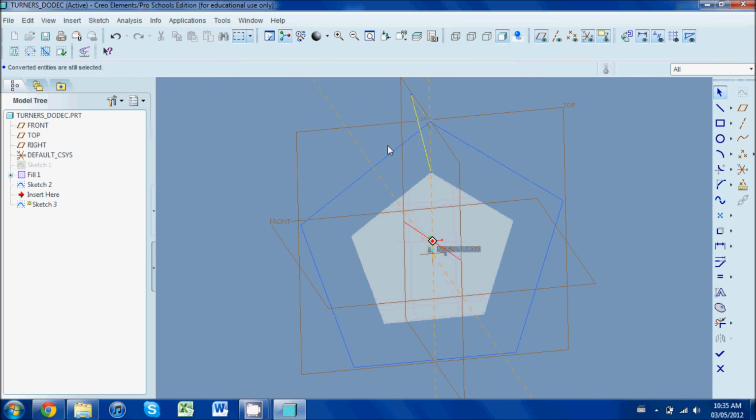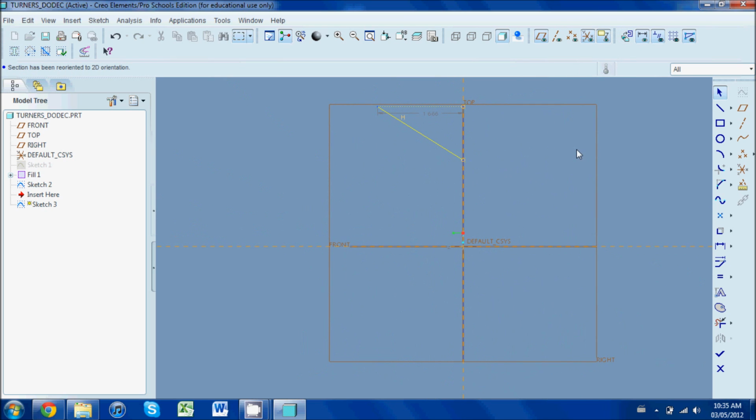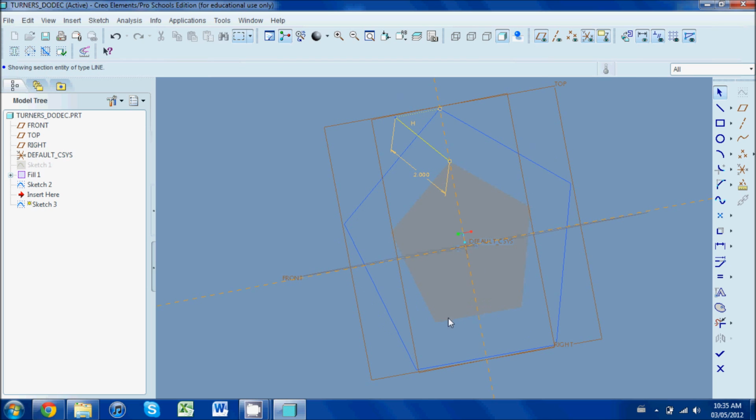if you can imagine folding up another pentagon here, here, here, where all the edges touch, there's going to be an edge line right here, and we're going to use this to create our datum plane that we're going to then sketch our next pentagon on. So we're going to go over here to the dimension tool and click, and then just middle mouse click out here somewhere, and now it gives you the dimension. Now if you remember in the first video, we set our base as 2 inches, meaning this edge length is 2 inches.